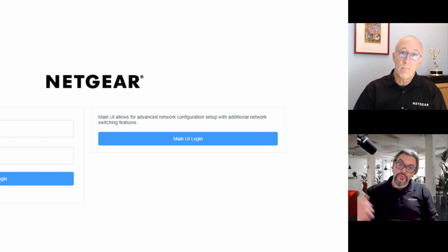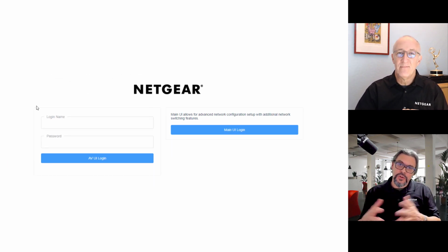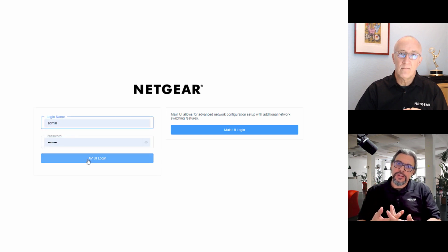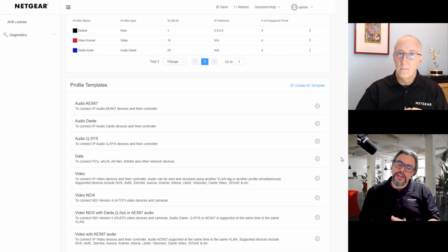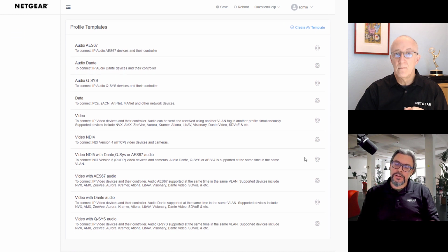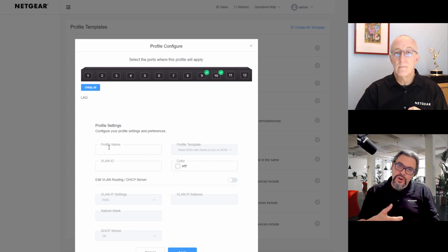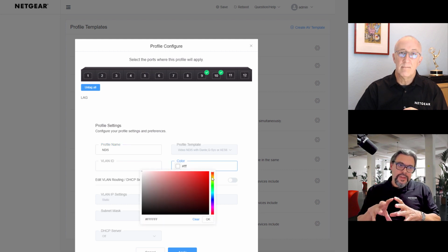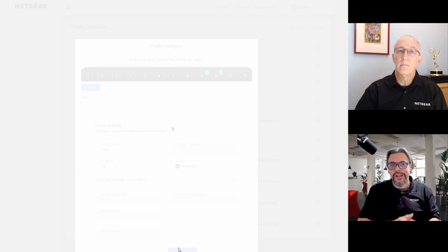Oh, yes, John. And if you want to get lost rapidly, please do it. And you will see that all that is configured. So take it simply. The EVUI is a list of certified profiles that are mutually certified between NETGEAR and these AV over IP manufacturers that partner with us. And this is good because this way you don't have to figure out anymore what you need to do for AVB or what you need to do for Dante or for VLX or AMX or NVX. So with this, you just tell the switch what to do. And this interface is just sending all these commands to the switch.